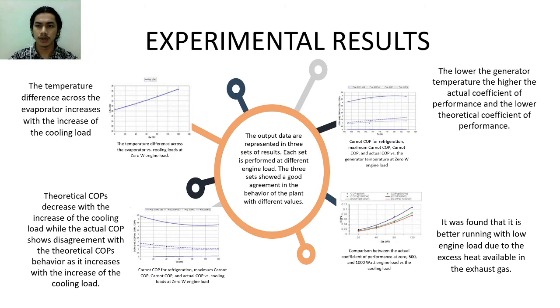Then, the lower the generator temperature, the higher the actual coefficient of performance, and the lower the theoretical coefficient of performance will be. It was also found that it is better running with low engine load due to the excess heat available in the exhaust gas.